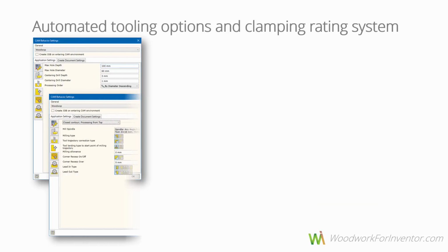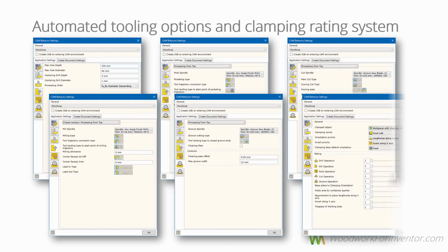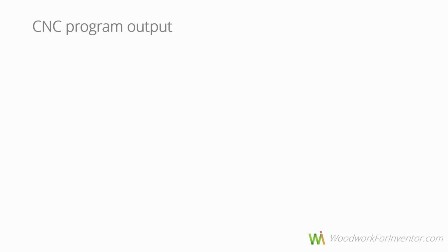And then you need to teach your machine how to behave in case you need to, let's say, do a milling or cutting operation. What are the priorities when you place something on the machine? How to behave if you place a workpiece with oversizes? What is the operation priority? What is the ratio for operations, and so on. Normally this should be done only once, and once it's done, you can generate CNC programs from the model. And how does it happen?